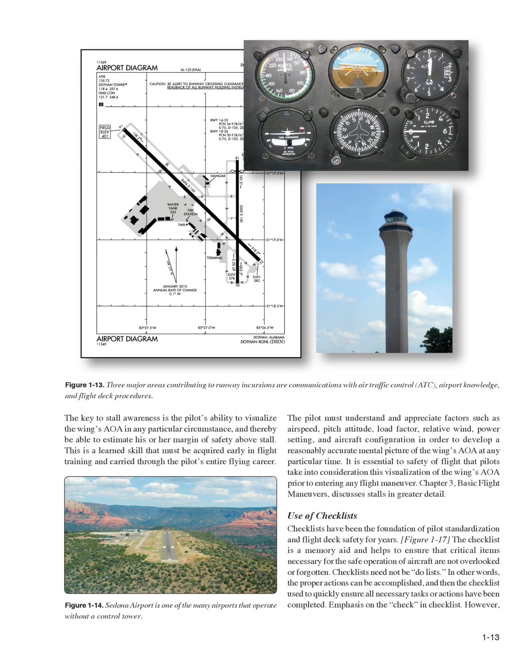The key to stall awareness is the pilot's ability to visualize the wing's AOA in any particular circumstance, and thereby be able to estimate his or her margin of safety above stall. This is a learned skill that must be acquired early in flight training and carried through the pilot's entire flying career. The pilot must understand and appreciate factors such as airspeed, pitch attitude, load factor, relative wind, power setting, and aircraft configuration in order to develop a reasonably accurate mental picture of the wing's AOA at any particular time.